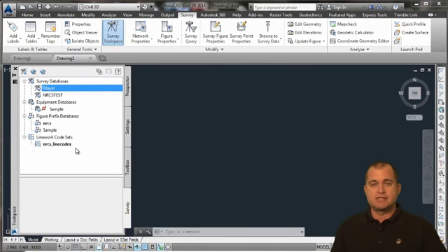The line code set is needed to tell the lines when to start and stop, add curves, close, and whatnot. We'll get into that. The figure prefix database tells the figure whether it's a break line or not, what layer it should go on, and what style should be applied to that figure when it's created.